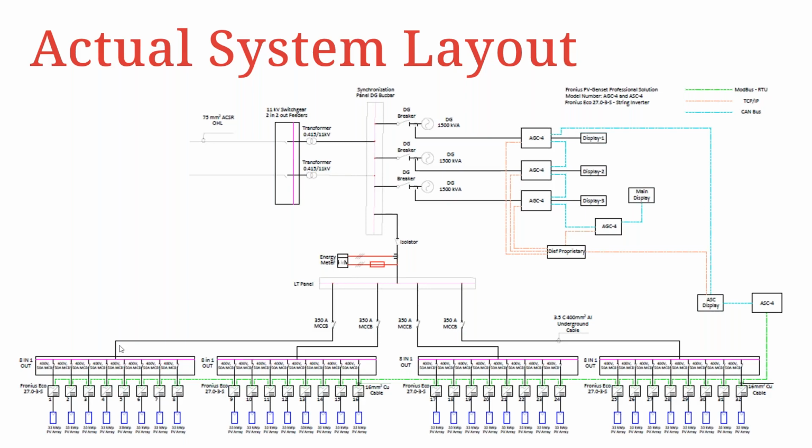You'll then have one master cable running from each PVDB to its LT panel, where it's effectively tying in, as well as its main breaker for each separate individual PVDB that's being fed into the system. Here you can also see the energy meter that's helping to monitor exactly what flow of energy is occurring. Another important thing to note is the communication side.